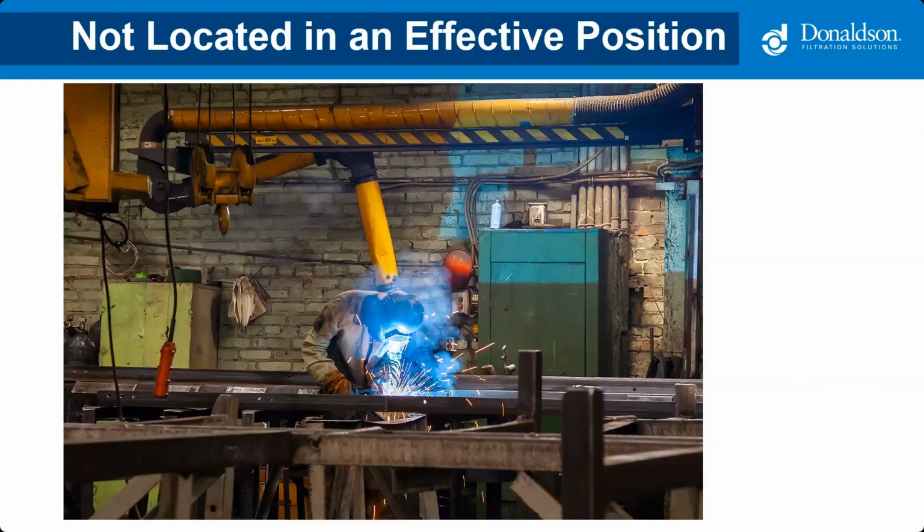Those weld extraction hoods are extremely effective when they're used properly. If you have a part on a jig that you're going to weld 200 parts a day at a table, they're great because you can put that weld fume hood right behind the part, do your weld, and go through the systems.